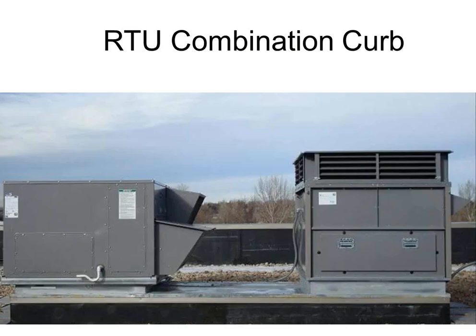It allows us to route the return air through the ERV and out, and then bring the outside air through the curb and into the rooftop's return section. So this is an extremely cost-effective way to do it. Yeah, it's a little bit ugly, I agree, but it's on a roof, and no one sees the curb unless they're on the roof, so it's not a big deal. But it does allow us to use packaged, standard, off-the-shelf rooftops with the ERVs and get the best of both worlds in terms of first cost and energy savings.